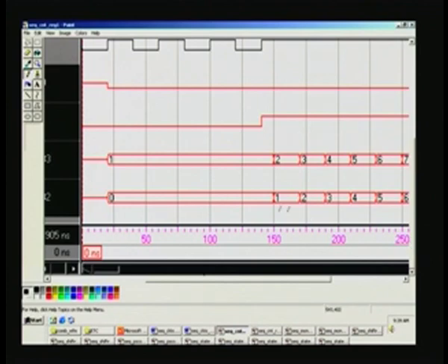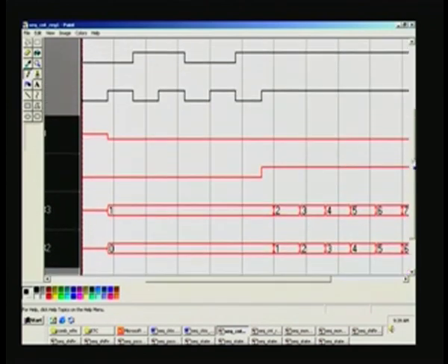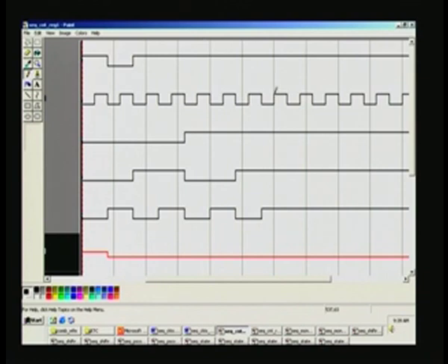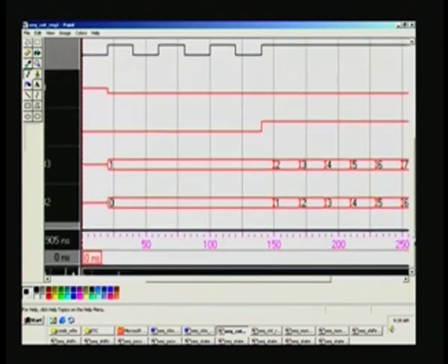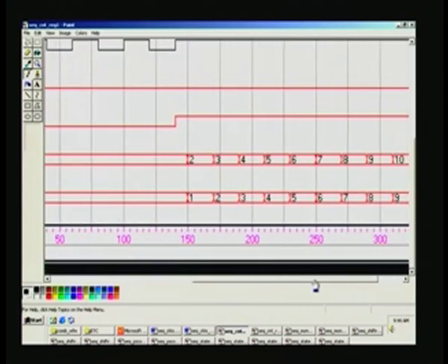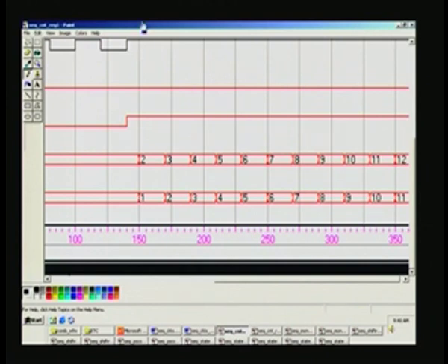So, you can see that this is the edge that is at 150 nanosecond, and corresponding to that clock has become active there. That is a rising edge of the clock is noticed, and here ABC conditions are 1 here, 1 here, 1. This is ABC, and reset is no longer active. It is active during low phase here, and you can see the counting progressing smoothly by 1 at every clock pulse. If you have a look, it will be a clock pulse here. So, rising edge of the clock pulse here, and once again it will rise here.